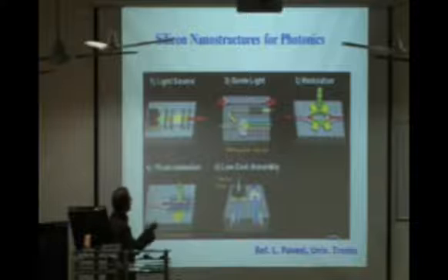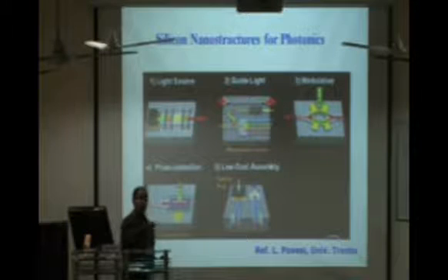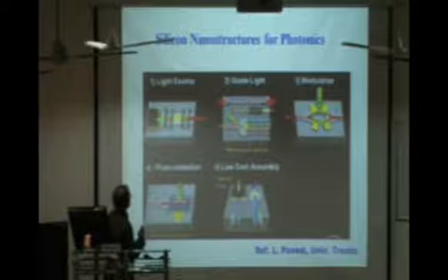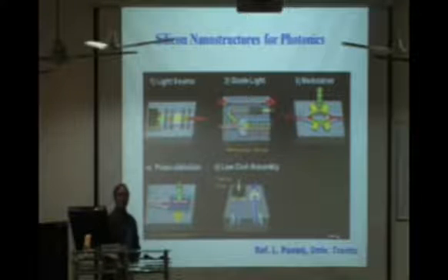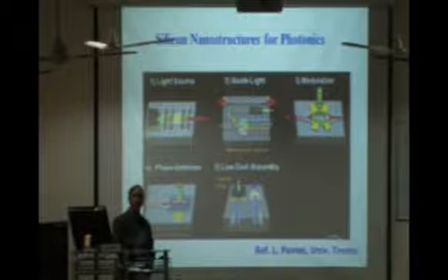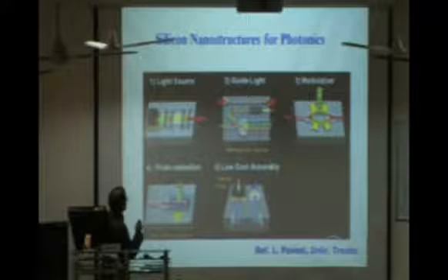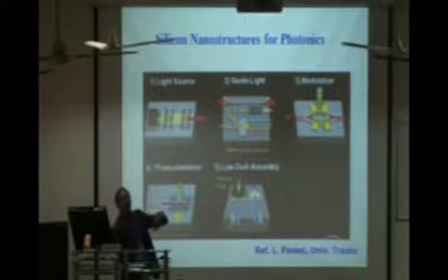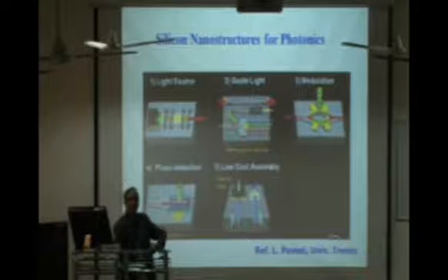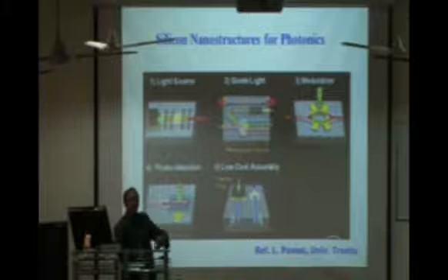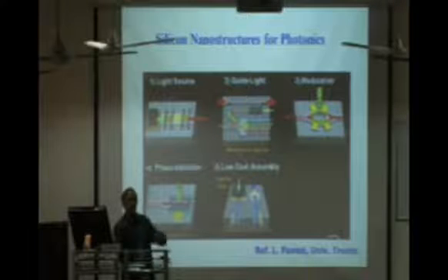And the second part of my talk will be a little bit more about the research that we are doing using some kind of quantum dots. One of our motivations, as I said, is that we still don't have silicon lasers. If you have silicon lasers, even if you cannot make the quantum computer, you can make the optical computer. So one thing is whether this can be done by making quantum dots or nanostructures. Silicon is an indirect bandgap semiconductor; if you make a strong quantum confinement, is it possible to break the so-called selection rule of transitions, and get some kind of emission from silicon or germanium?